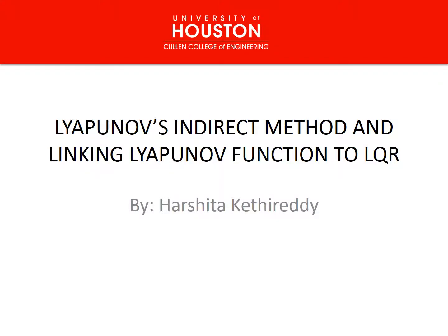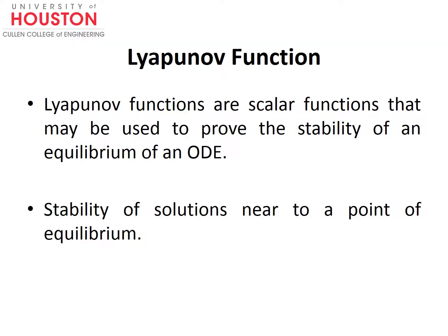Hello everyone. In this video, I'm going to go through Lyapunov indirect method and linking Lyapunov to linear quadratic regulator. A Lyapunov function is a scalar function defined on a phase space which can be used to prove the stability of an equilibrium point. The Lyapunov method is applied to study the stability of various differential equations and systems. One can think of the Lyapunov function as a generalization of the idea of energy of a system.